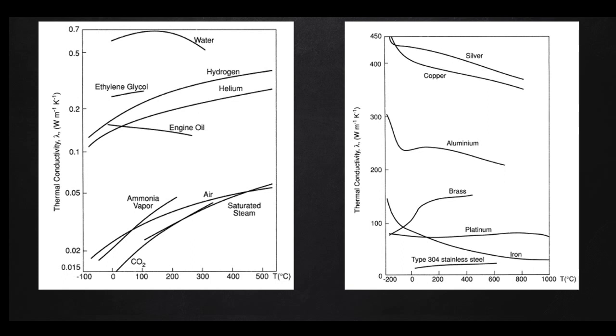Now, have a look at these two graphs. Let's look at the thermal conductivity for liquids, for example. Take CO2 at the bottom. Let's say the temperature varies between 100 and 200 degrees. It is apparent that a linear correlation could be used to estimate the thermal conductivity, but look on the right-hand side and see that the thermal conductivity does not vary all that much, and so we would actually just be splitting hairs. So why not just take the average of the thermal conductivity between these two points?